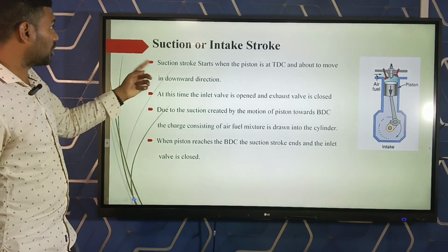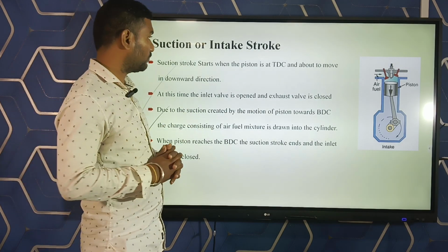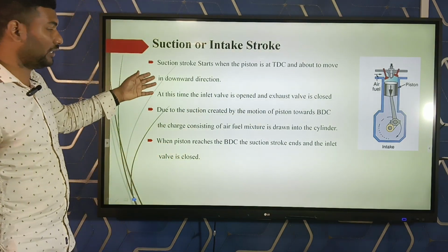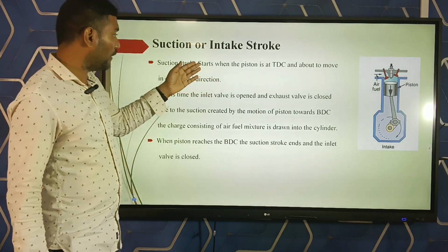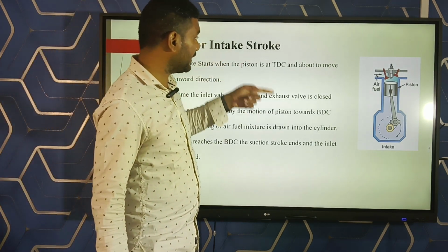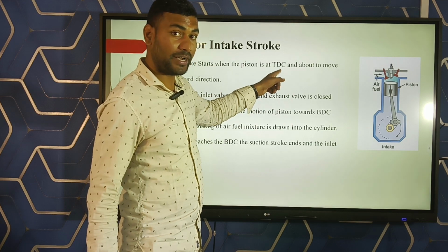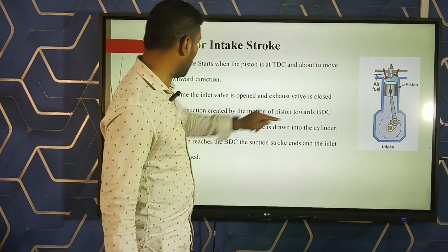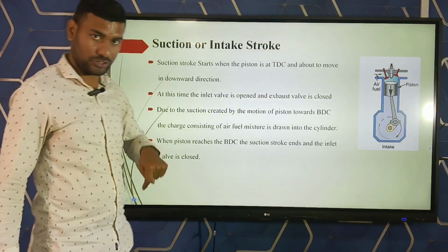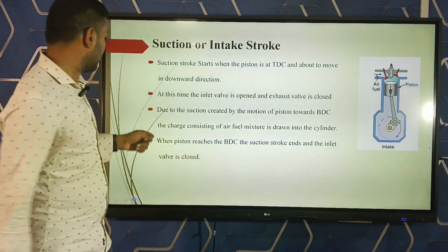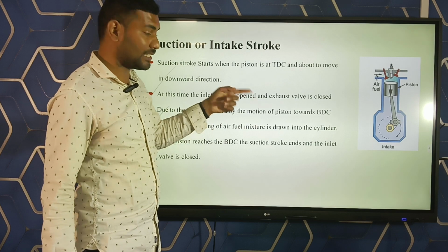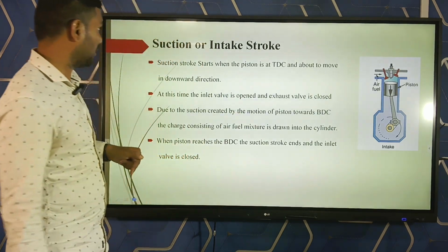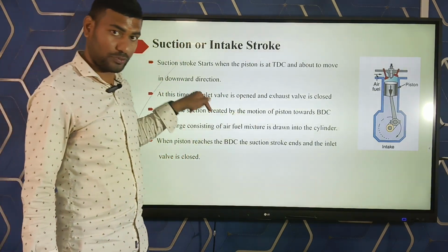Next, suction or intake stroke. First point is the suction stroke starts when the piston is at TDC, means top dead center, and moves in downward direction. At this time the inlet valve is open and exhaust valve is closed. This is the suction process only.